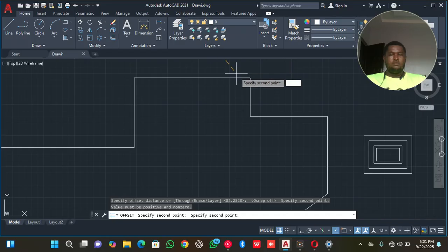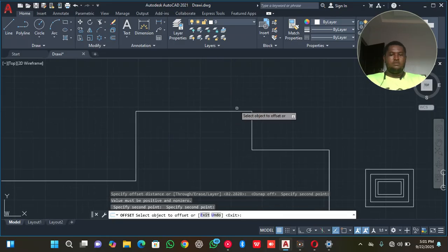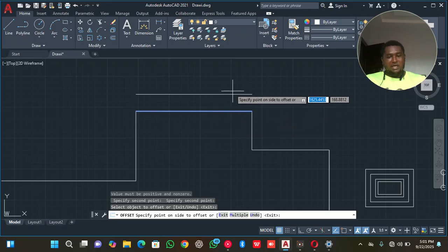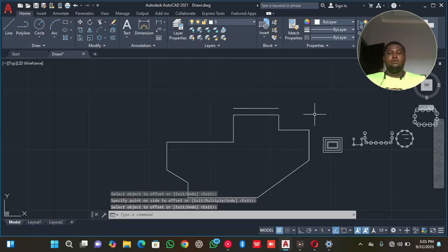So in your laptop, when you highlight the object you want to offset and you click offset, type in the number, the distance between here and here that you want to offset the distance at. Okay. Let's click enter. There's something I want to try.